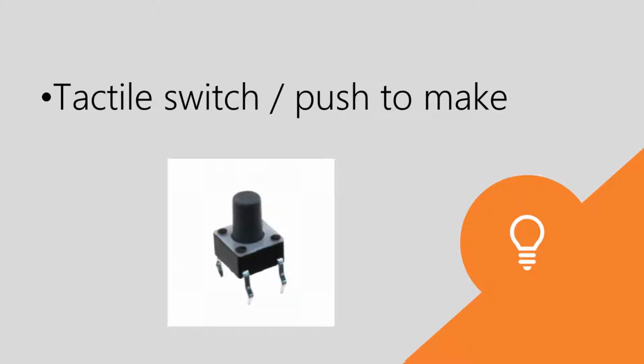However, there are other variations whereby it works in the converse. When you press it, it breaks. When you release it, it makes the circuit. You can configure it another way around, because this switch already has some points which are already in contact, and when you release it, those points release their contact. Either way it can work.